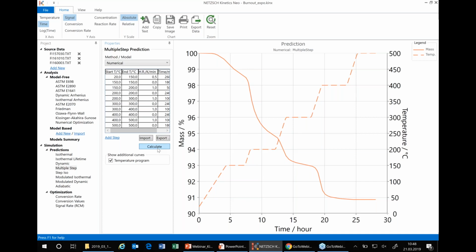Firstly, what does the best quality mean? Best quality means that we should have a good structure of material. For example, if we have debinding too fast, then the production of gases will be too fast, and the gases have no time to go out of our sample. And there are bubbles inside the material, and these bubbles can have a high pressure and can damage the structure of the material, and the quality of the material will not be so good.